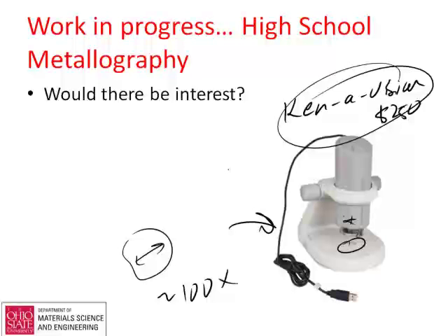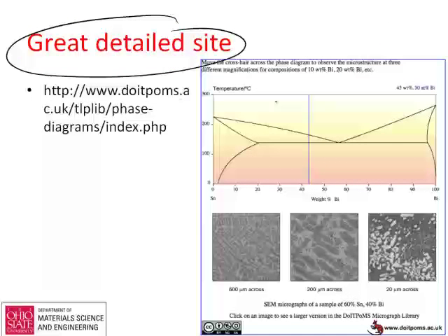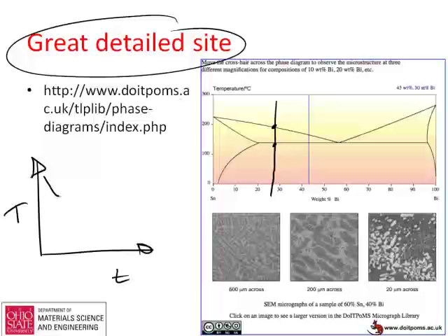The other thing that the Cambridge site brings up nicely is, as you go through these phase diagrams, as you cool down, you fix the composition, and as you cool with temperature, if you plot temperature versus time, you actually see inflections here and here, and you see the cooling rate. As you start to form solid, you see an inflection. When you hit the eutectic temperature, you see an arrest where the temperature doesn't change with time at all, and then it continues with the initial slope again.